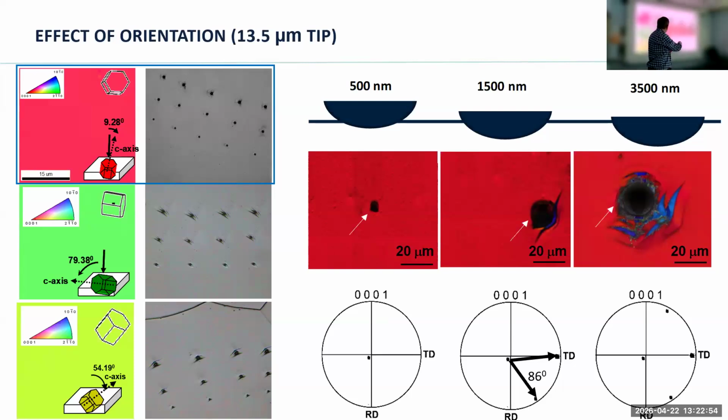So we'll look at the indents. So this is the first case. And what we see are these blue things here, which are twins. So it's when the crystal in magnesium flips 86 degrees when the twin happens. Okay, so in the pole figure, you can see from the initial orientation in these twins, the orientation is rotated out to the edges. And in principle, there are 6 variants of these twins, and sometimes you'll see, in fact, 6 different twins that have formed.